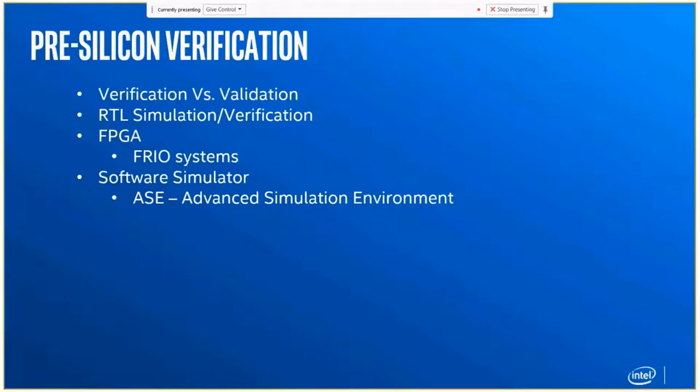In FPGA, kind of, but FPGA verification is more to ensure that the chip design at the RTL level did not miss something, that it's faithfully doing what it's supposed to be doing. Whereas the software simulator takes that input and creates a simulator that the customer can replicate as many times as they want on each PC they have. Each application developer can have a real application developed. They can run it and make sure it works correctly. And finally, when the actual device comes out, you can run the same application and it will automatically run. It's guaranteed to work that way, right?